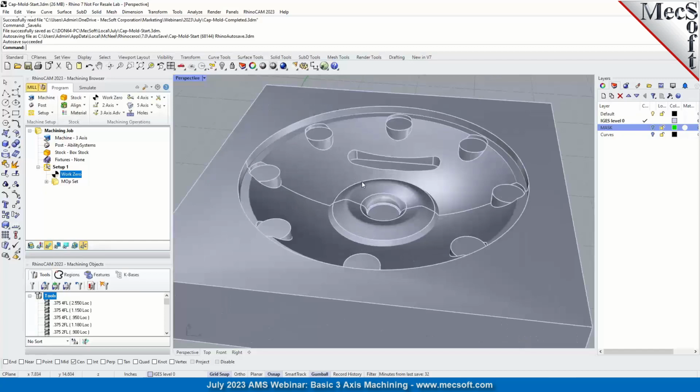Basically, in most cases, if you're designing the part or designing the mold, you're not the one that's going to be actually cutting the runners. That's a highly specialized process where a dedicated engineer will determine the mold flow and the characteristics of the plastic, etc. They determine where the runners are going to be, how large they are, how big the gate is, etc. So a good mold shop will prefer that you don't put any runners and gates and let them do it themselves.